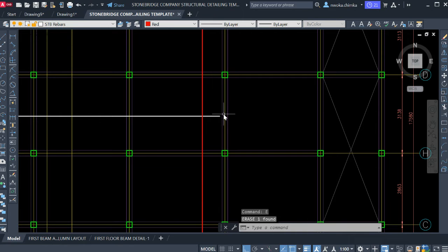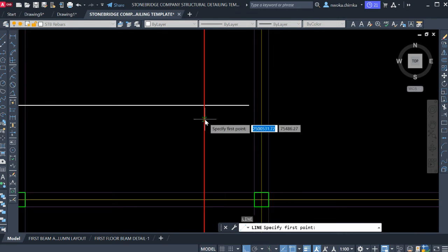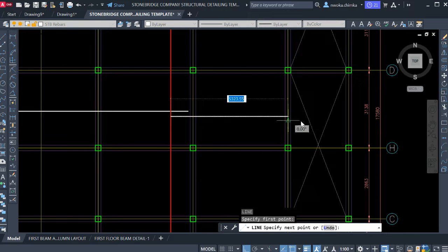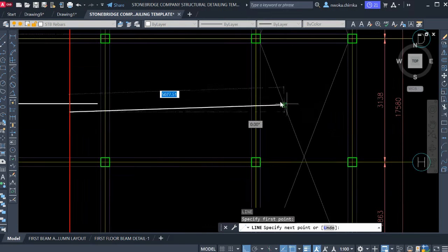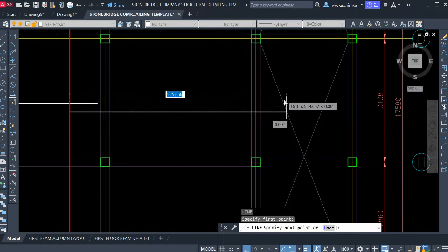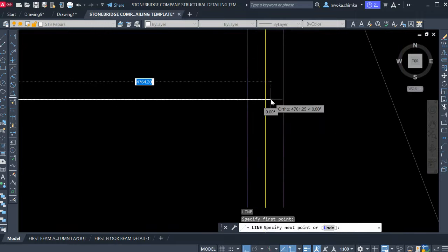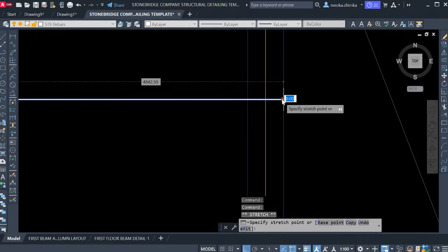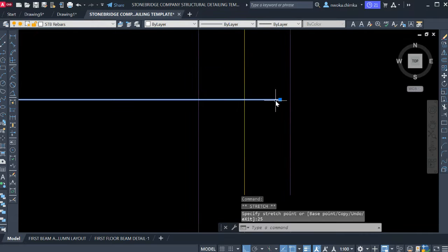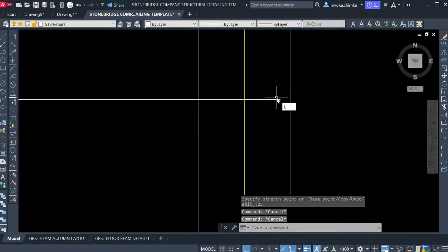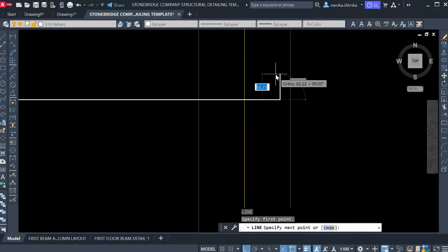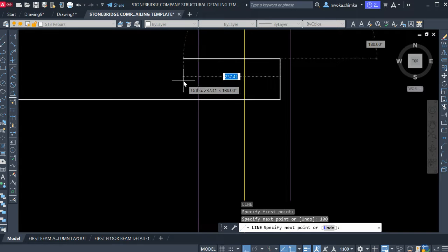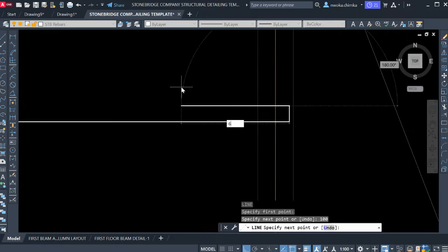So what happens right now, now click back and change this to layer, and draw my next bar from this point right now to this point of staircase. Since this is a staircase, this reinforcement cannot pass through the staircase because here is a void, so it will just have to stop here, and then click on this point to remove my cover of 25, and then I will now click on line, then click to put my bent up 100, and then put my lapping of 600.